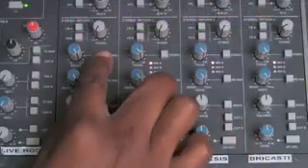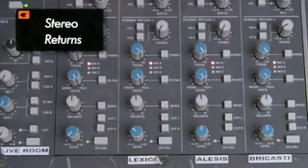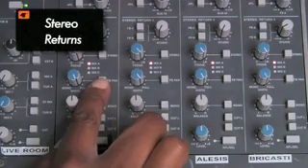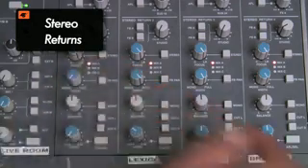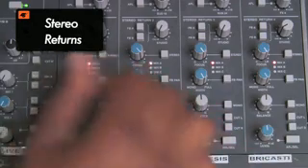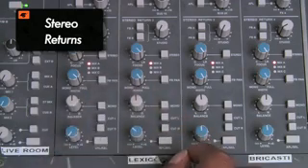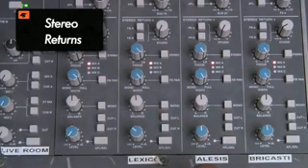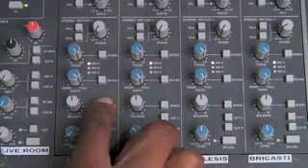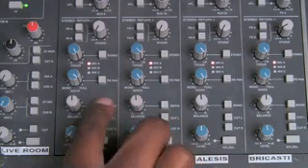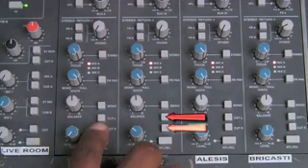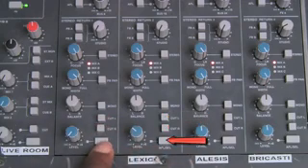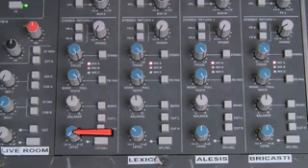Over here we have the stereo returns. These are used, as you can see by the labeling here in the studio, as returns from our effects units, and all this is also accessible via the Patchbay. It has 4 stereo returns. Each stereo return can be assigned to either mix bus A, B, or C. You can choose to have the effects return as a mono signal and also cut the left or right signals. And you can also listen to the AFL signal. Beside that, you have your level control, which controls the level of that effects section.